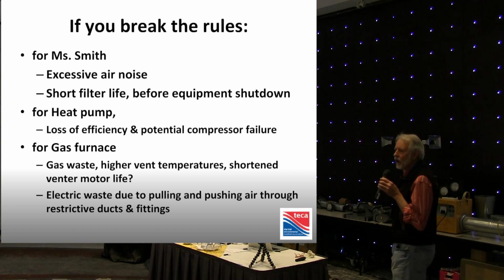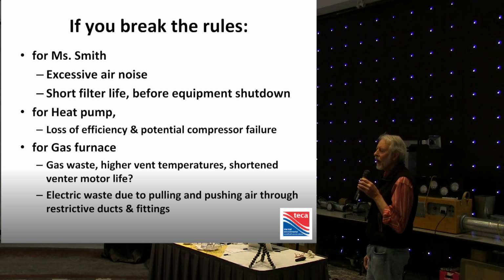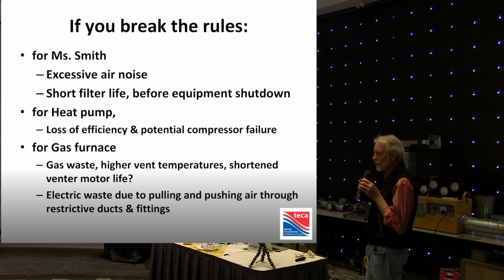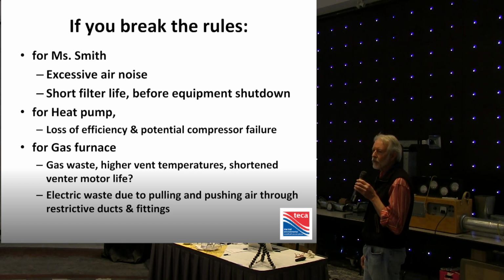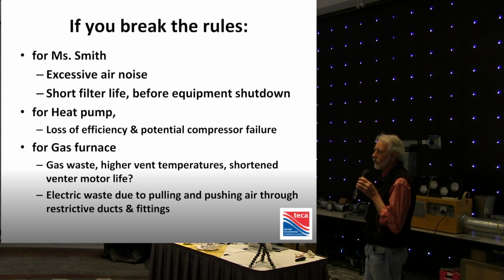For heat pumps, what's not commonly known, and I'll get into it at length, is that heat pumps are air-sensitive equipment, and a lack of airflow puts your compressor at risk. And the compressor is the biggest single cost component of a heat pump. When that compressor cooks, it often contaminates the system, with the refrigerant being contaminated with all sorts of garbage from the compressor. And unless you spend very expensive money to purge that contamination from the system, you may cook the next one. You cannot ever cheat on airflow through a heat pump.